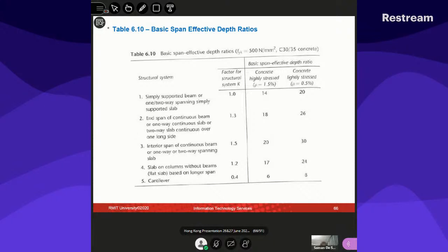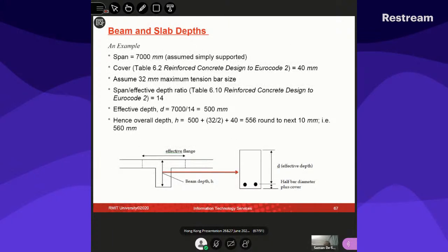So if you have, rather than 5 meters, 16 meters, what that means is that your ceiling height will be lowered, or you have to have a bulkhead to make sure that the sewer pipe can go through within the ceiling cavity, between the ceiling and the concrete above. Those types of things are the objective of this scenario.